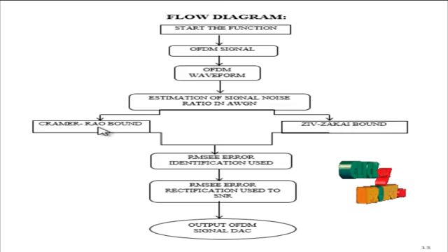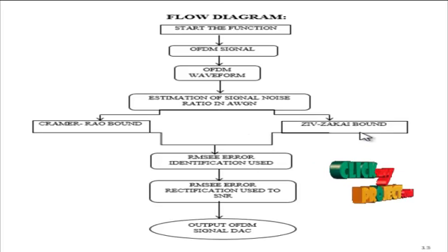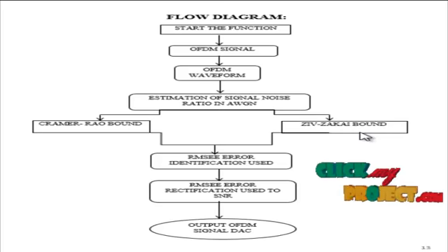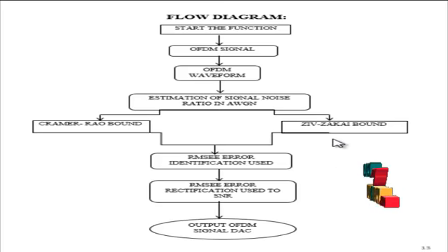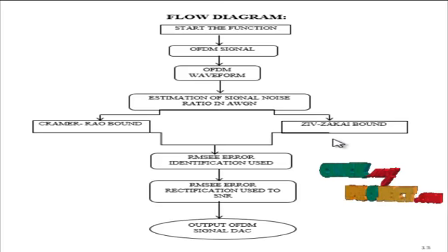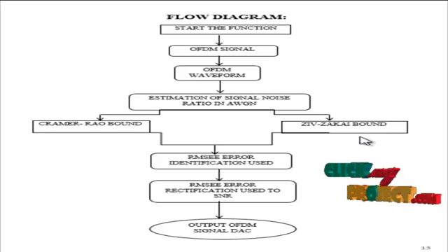Next, in the Cramér-Rao bound and Ziv-Zakai bound, the characterization is performed by properly shaping the power spectral density of the OFDM signal so as to infer the influence of the subcarrier power distribution on the TOA root mean square estimation error using the Cramér-Rao bound and the Ziv-Zakai bound model.